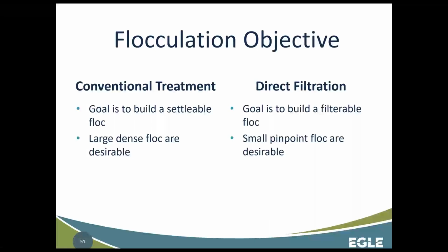Direct filtration, we're just looking to get rid of that charge, maybe increase the size a little bit, but we don't want big floc because we need to be able to take advantage of the depth of our filter. If we apply a large sweep floc to the top of the filter, we're only going to be able to take advantage of the very top surface area of the filter. None of these particles are going to be able to migrate down and adhere to the media at the greater depths of the filter.